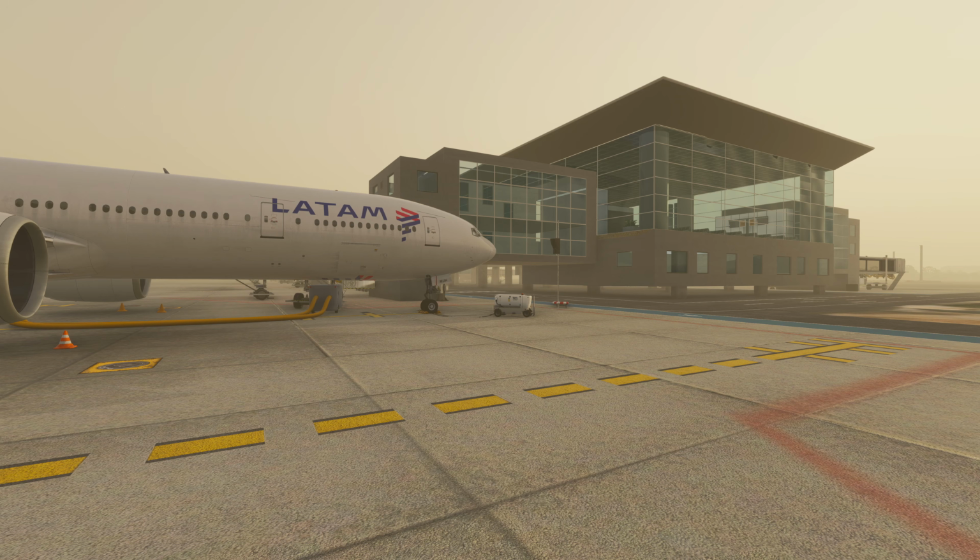In most places around the world nowadays, there is a requirement for you to keep the APU off when you are on the ground. So a few minutes after airplane arrival, you need to take your APU off. To take your APU off, you need an external ground power unit and one external air conditioning unit in case the temperature is too low or too high.